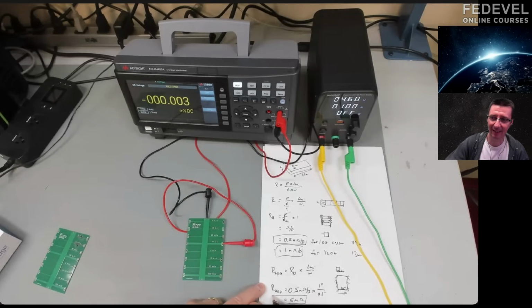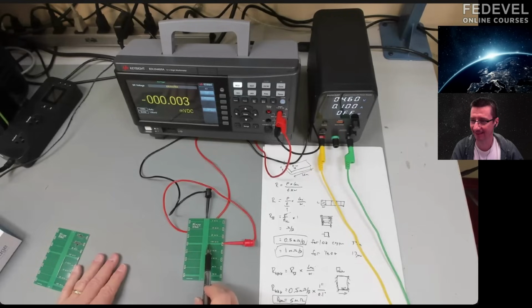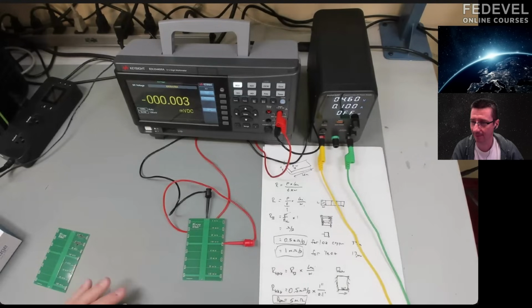Yeah, it looks like we can fit 10 widths. Exactly. From here to here is 1 inch, 100 mils wide, so we get 10 squares down the line. This means that at a glance, if you can look at your trace and estimate with your eye how many squares you can fit, that times the sheet resistance is the resistance of a trace. Trivial to do in our head. So we expect for this trace 5 milliohms.